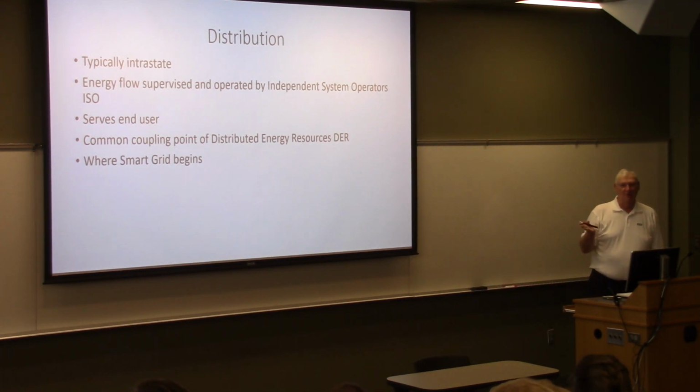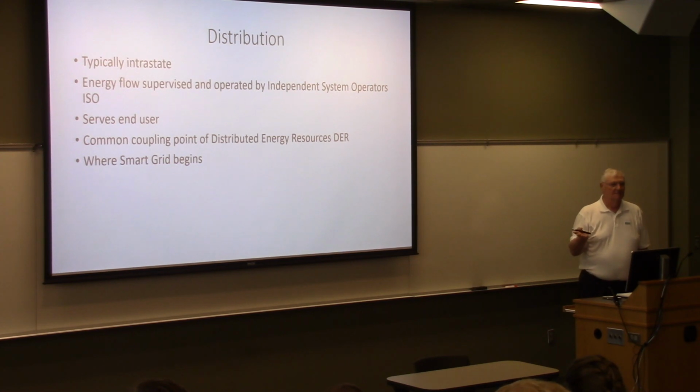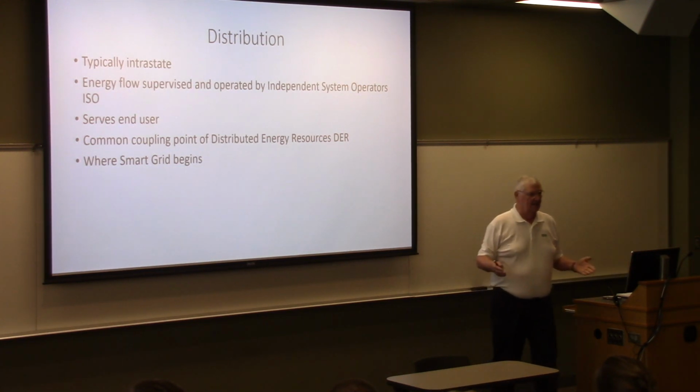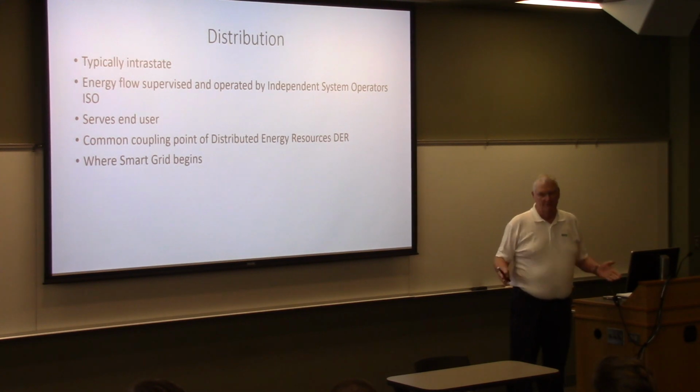Anybody have an idea what the smart grid is? Basically, the smart grid is a system of wide area monitoring to more accurately do demand response, so you can waste less power and generate exactly what's being used. The system already does that. The system is a real-time energy system. Energy in equals energy out all of the time, or you got problems.